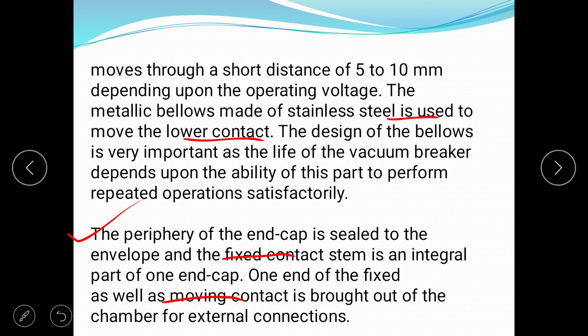Now the advantages of vacuum circuit breakers. Basically, a vacuum circuit breaker is self-contained and does not require filling of oil and gas. They do not need an auxiliary air system, oil handling system, etc. Next, rapid recovery of very high dielectric strength on current interruption, so that only half cycle or less of arcing occurs after proper contact separation.